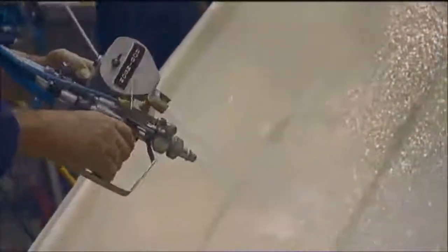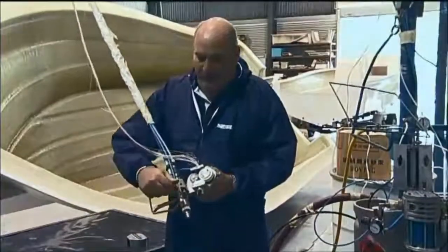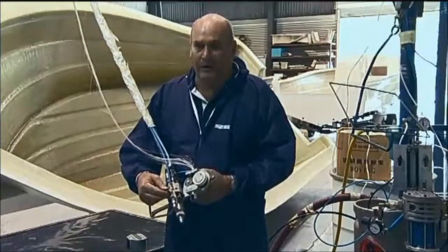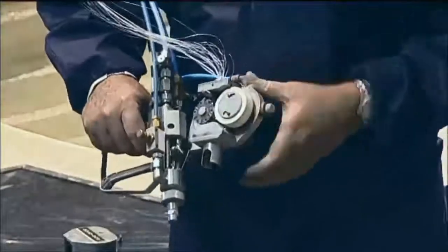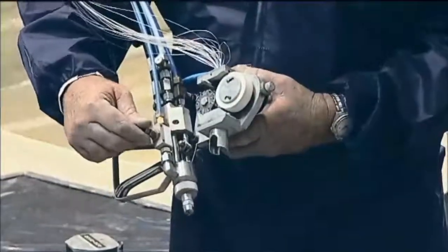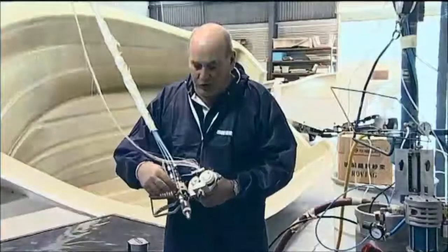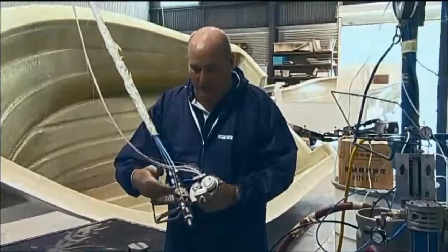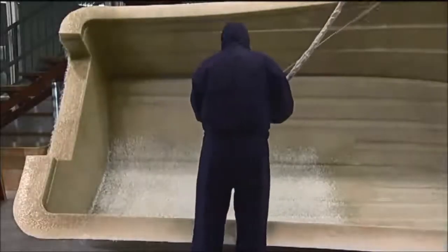Now, being an internal mix, we need, as I said, a solvent flush. This bit here, this is an atomizer. Okay, so unlike the airless systems we're using in a gel coater, they're not relying on air to atomize, to create a spray pattern. By reducing the amount of air, we can reduce emissions. So as part of the training for gun operators, they learn how to control emissions.